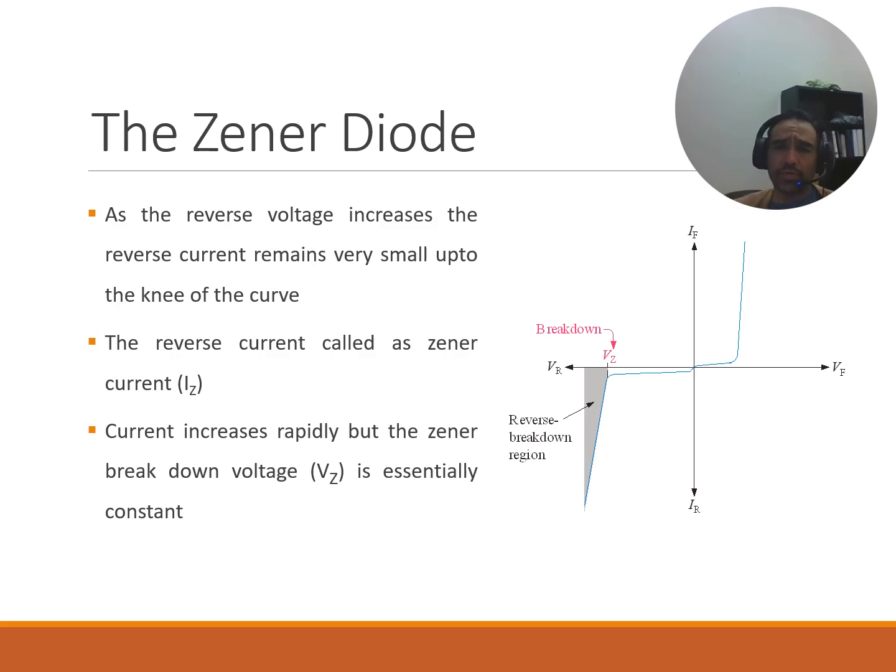A little bit of a step up for an explanation on the reverse breakdown region. Again, the Zener diode is designed to work when the electricity tries to flow in the reverse. Normally, electricity flows in one direction, but when it tries to go backward, the Zener diode helps control the voltage by allowing a steady flow when the direction is reversed. That's what makes this a special purpose diode. And this special situation is called reverse breakdown region.